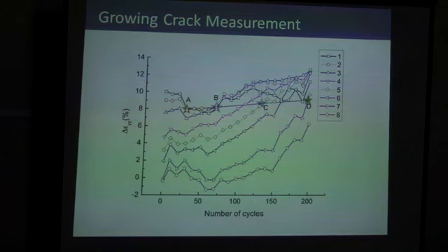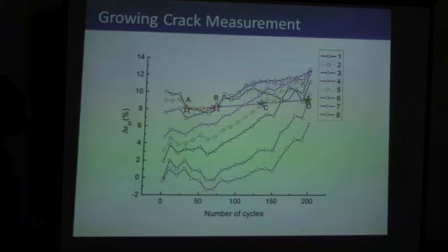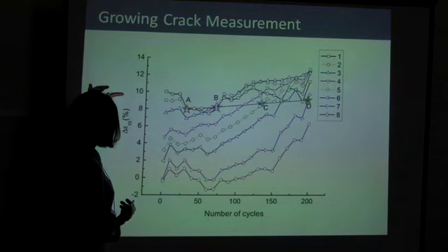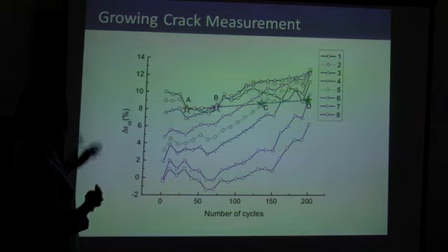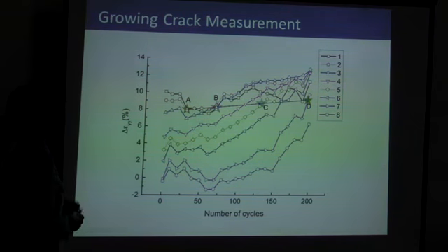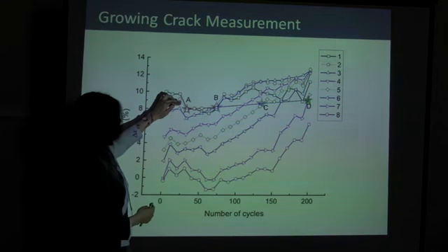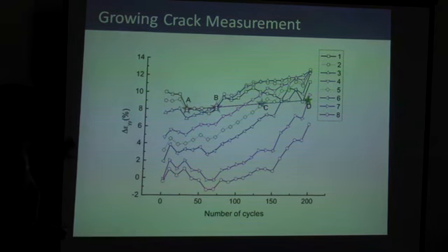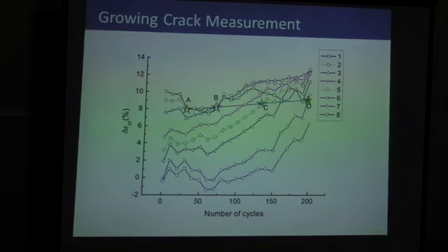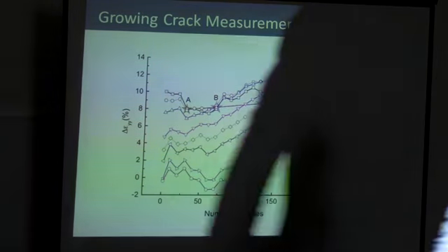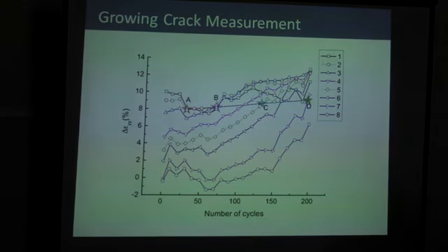And if you look at this point, although these are discrete point measurements, you will see that the value is more or less similar, about 8 micron. And this indicates the crack tip position. This value is actually similar to the value that we reported previously, with a slightly higher, slightly lower K value. So they might have some meaning, I don't know, for this particular theory.